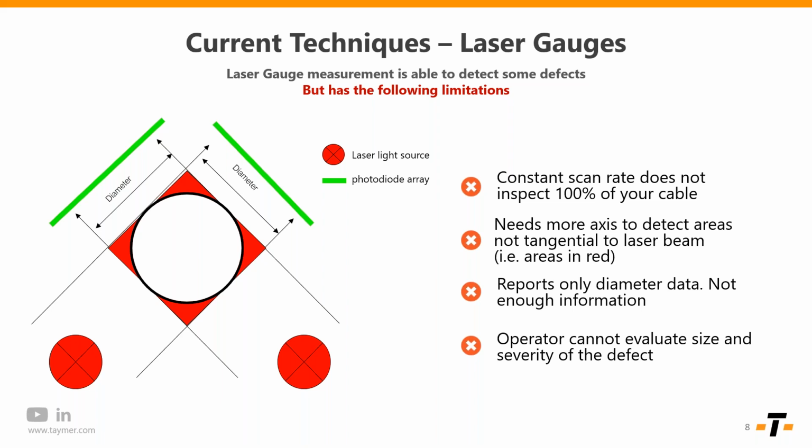The SI is also capable of looking at multiple things: diameter, lumps, neck downs, and surface defects. The biggest portion of it is that you get that image, with a timestamp telling you where in the run and when it was taken, and you can actually see the defect.